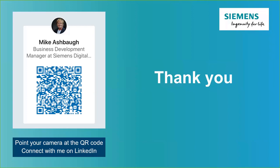Our first question that came in: I use Solid Edge Classic. Can I use that in the connected mode for ECAD, MCAD collaboration? Yes, you can use Solid Edge Classic to connect with Solid Edge wiring design. The key part there is you need to have that electrical routing part number added to your Classic license.